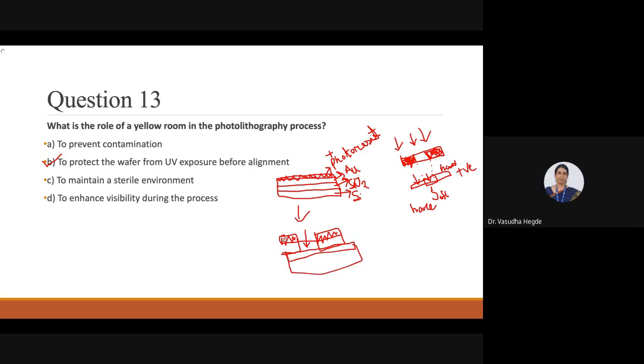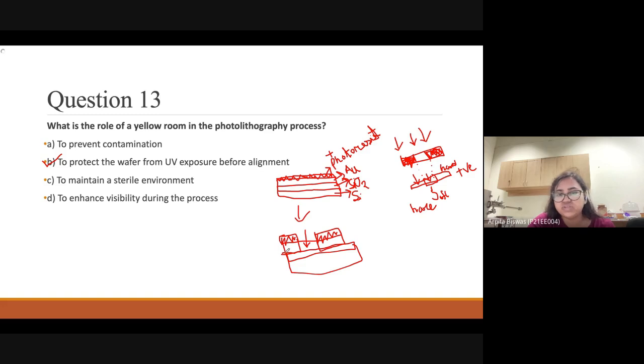So after that, we go for the photoresist removal process. We can use acetone or something else. So we will finally get this structure. This is the gold, because we remove the upper side where the photoresist is present. We will remove it by the acetone, and this is the gold structure.